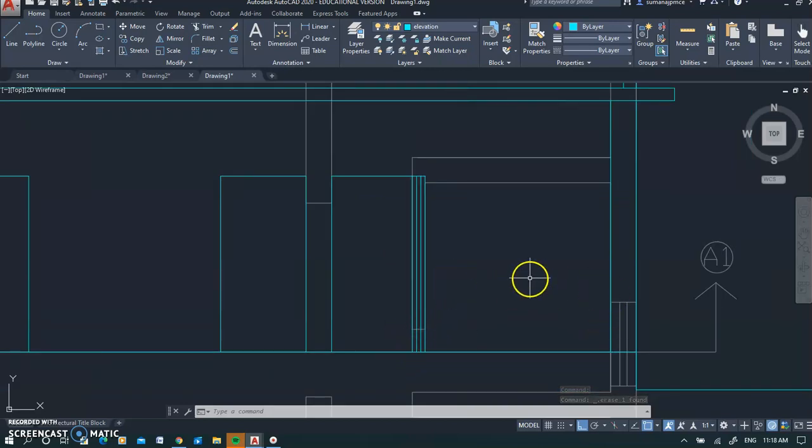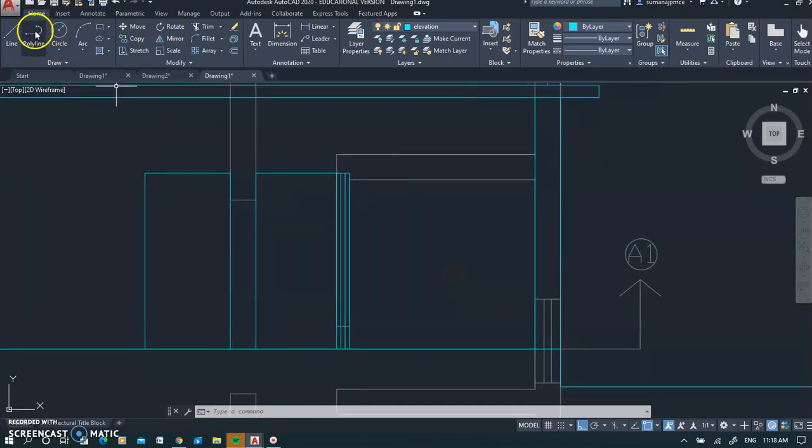That is the toilet door. Then we see the ventilator that is cut. So what we do is we draw a line. Height of the ventilator will be at 2.1, same as the door. And you will come down by, let's say, 0.6 is the height of your ventilator. And that's how it is. And you will see the two frames inside, exactly the way you see it in the